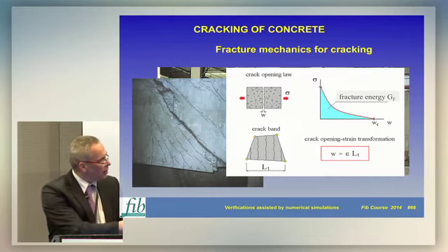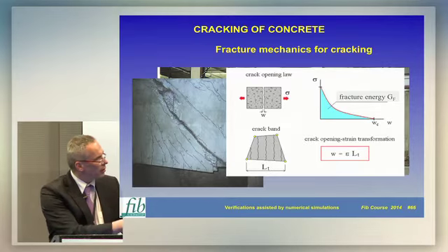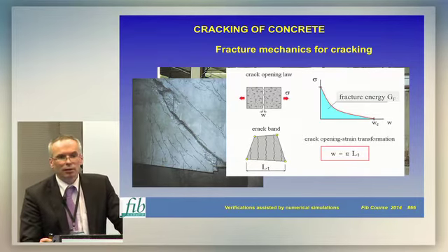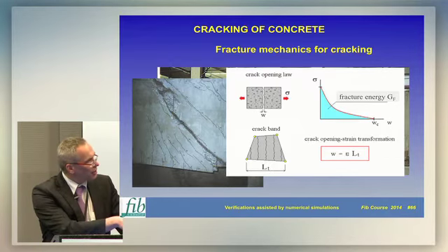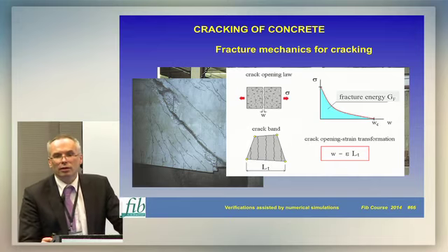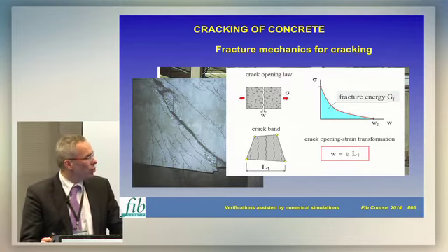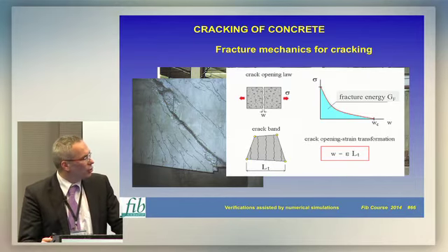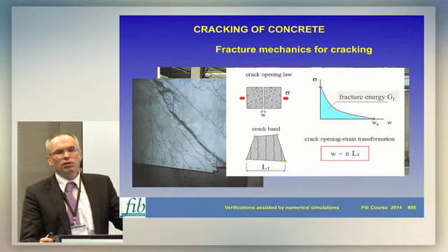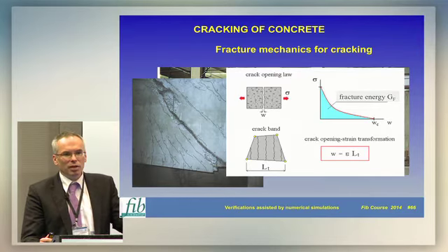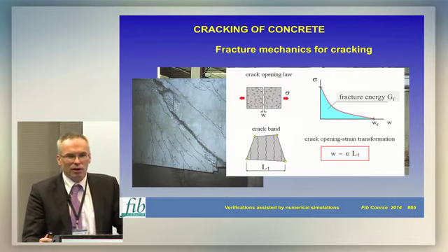The important parameter in this formula is the size of the crack band. In an ideal situation, we can assume that inside an element there will be one crack. And then we can say that this crack band size is the size of the element perpendicular to the crack direction. This is a good approach. It is also important that this crack band is calculated on the element level. In some softwares, it is an input parameter. But then it means that you should use finite element sizes which are more or less square and uniform all over your model, which in many situations is a very restrictive condition.